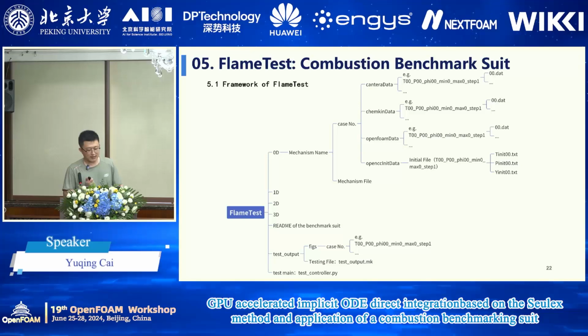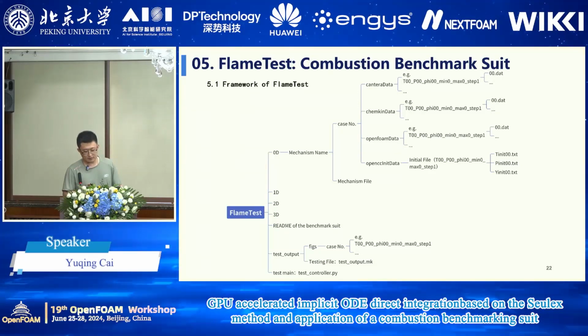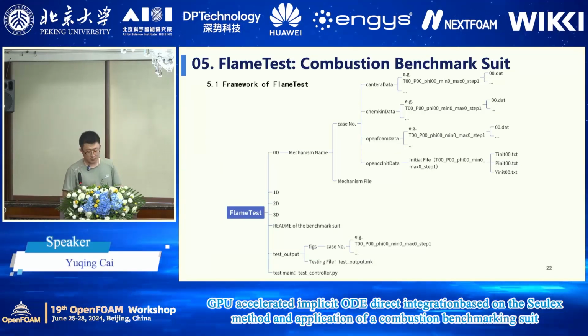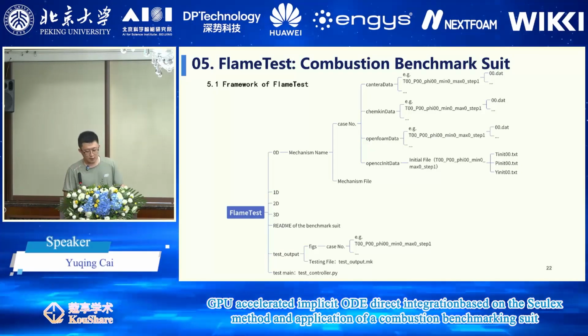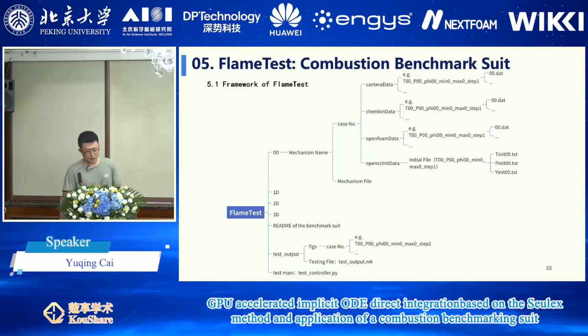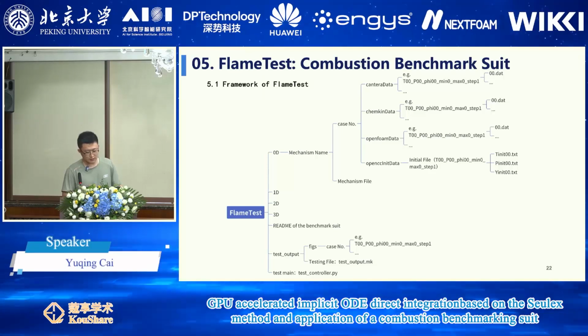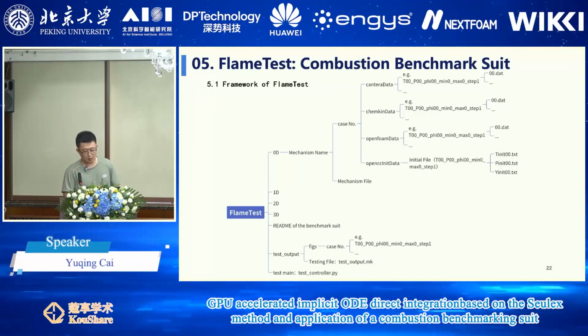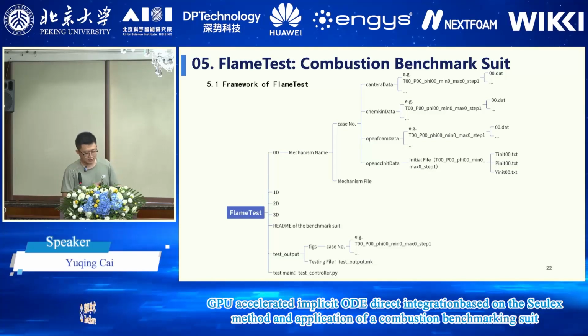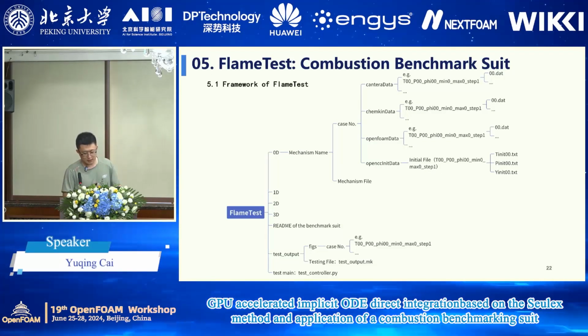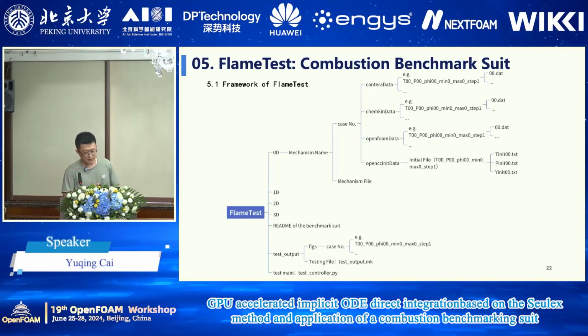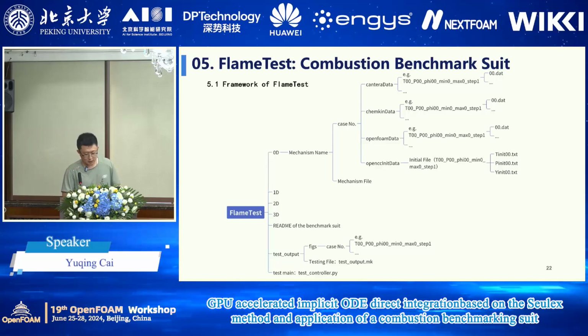In order to accelerate the development and verification of numerical software, we created a benchmarking suite named FlameTest. This repository integrates several reference data from classical solvers, such as Cantera, ChemKin, and OpenFOAM. The control module will invoke the test solver, such as the zero-dimensional test problem in OpenCC. It simulates the combustion process based on preset initial conditions and compares the simulation results with the reference data in this repository, automatically generating the comparison images and testing reports.